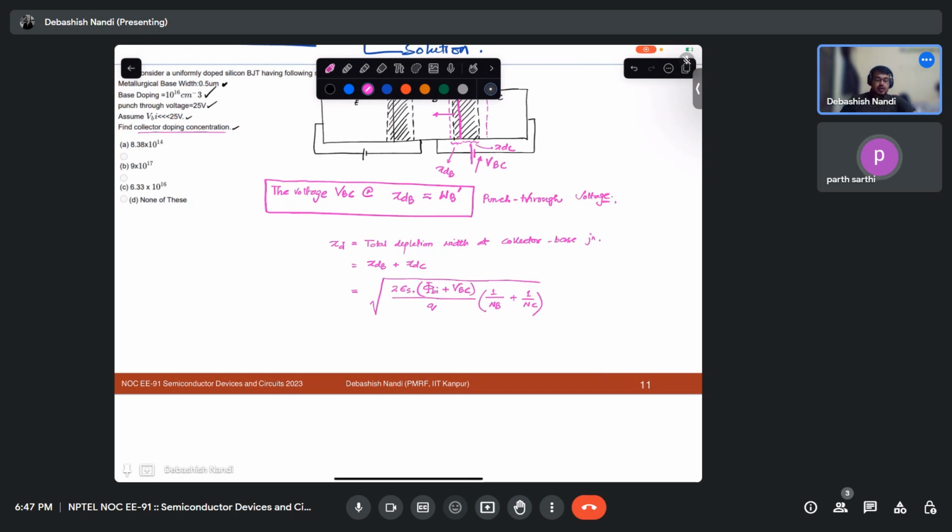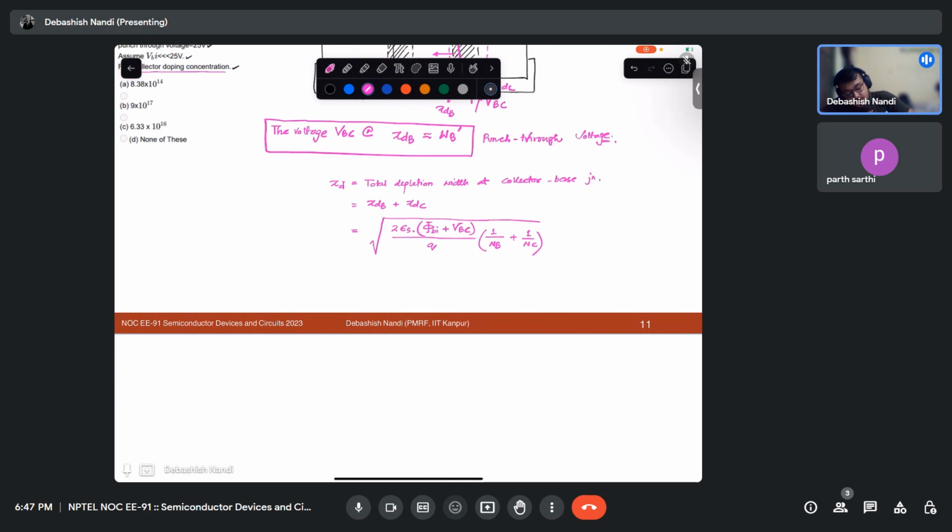Yes, sir. And also, we know from the PN junction theory that XDB times NB is equal to XDC times NC. Do you agree with that? Yes, sir. Why do you agree with that? How does that equation come about? It is nothing to do with electrostatics. It is the depletion approximation.